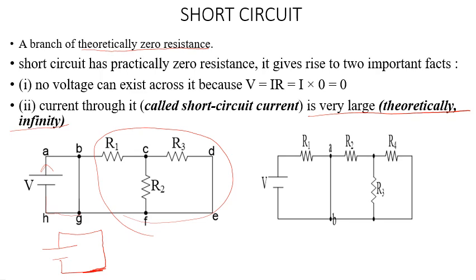So let's say this is our second example. You see that there's a short circuit here. Let's say current starts to flow from here. When it gets here, it comes to meet this node. From our definition, a node is where current splits. So when it gets here, current will not split, because at this node there's a free path here. It's just a free path, like it doesn't want pressure. So it just comes all the way back. Let me use a different color to denote it. This side of the circuit would not be considered in our analysis.